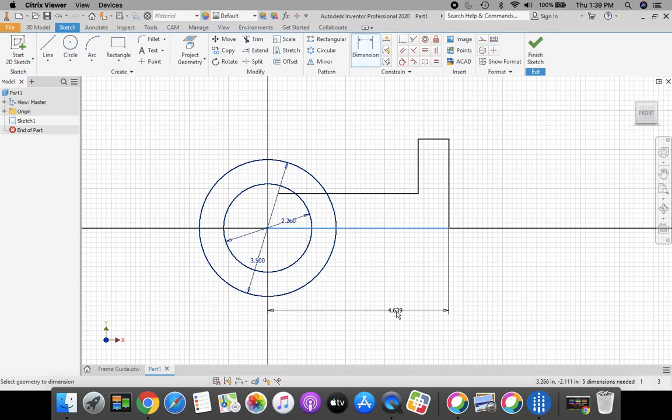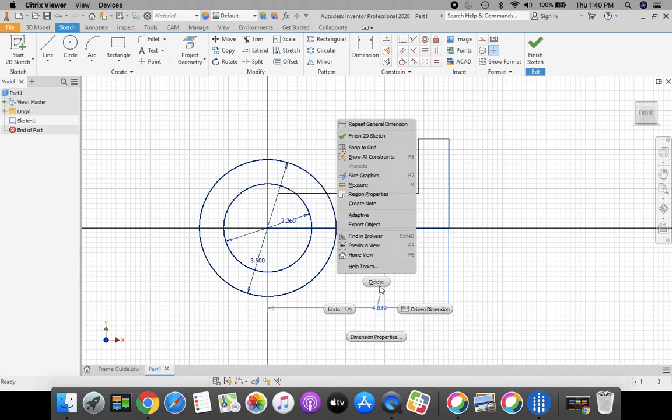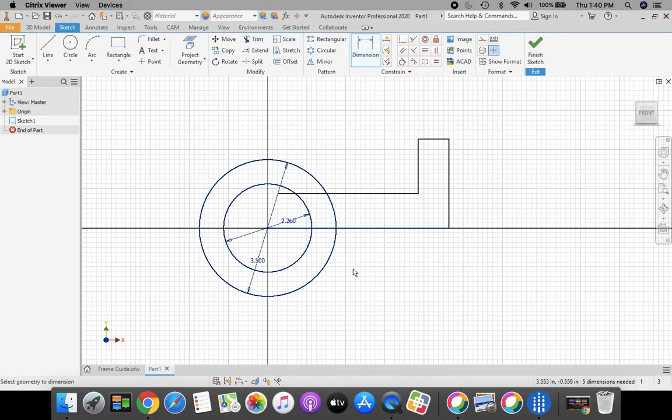I'm going to bring this down. And this dimension is, once again, dimension. I'm going to click on my origin when it turns red to this corner out here. Bring that dimension down. And this dimension is 3.5. Enter on the keyboard or green check mark.